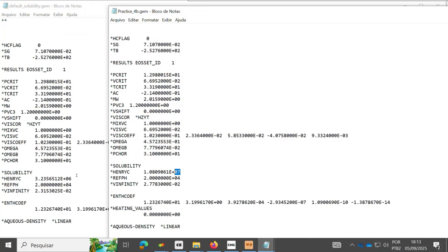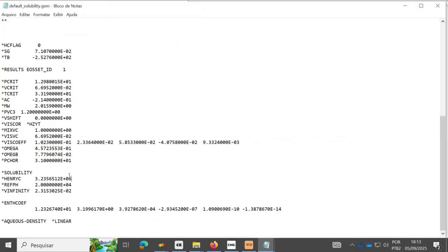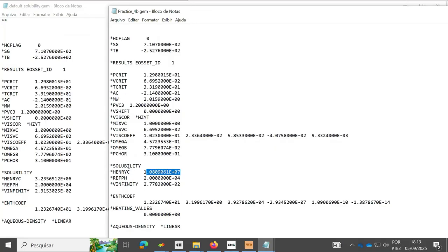The lab data, the data that I shared with you, show that the solubility is lower than the model was predicting. So this highlights how relevant it is to calibrate the model, okay? The partial volume is basically the same, the magnitude is the same, the numbers are very close, 2.3 and 2.7. But the key parameter for us is the Henry's constant, and the difference is too high. So it's very important to compare. I know that both numbers will lead to very low solubility. The amount of hydrogen in the brine will be very low.